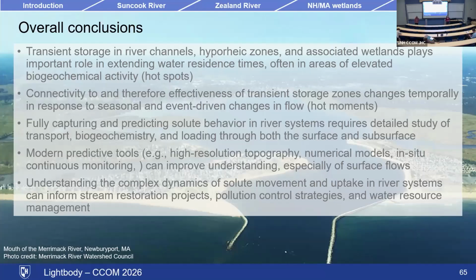I guess with a pollutant, the whole idea of using a solute, using a tracer to represent another substance, is that they behave similarly. With your example of a pollutant, maybe at some point you're bringing up this idea that it saturates and you can no longer remove any more. That issue of saturation of the reactive zones is sort of separate from this. This is assuming that the reactivity continues at the same rate, which, depending on the chemistry of what you're looking at, may be a terrible assumption.